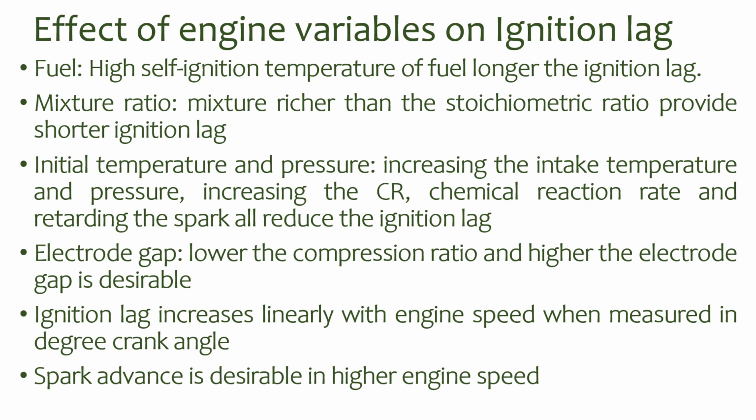Then mixture ratio: if the mixture is richer than the stoichiometric ratio, then the ignition will be faster, so the ignition lag will be smaller. And initial temperature and pressure, or the high compression ratio and the high chemical reaction rate, will all increase the speed of ignition. That means it will reduce the ignition lag.